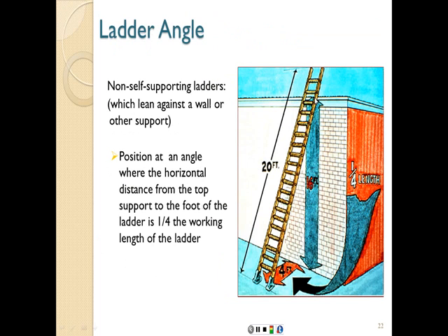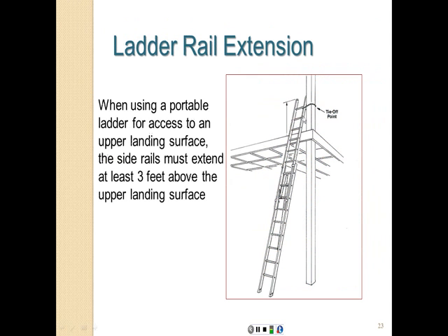This picture shows the 3 foot extension, so this is fine. But again, this one also shows the 3 foot extension, and it shows that it's tied off to prevent any motion of that ladder and allow for safe going up and down.